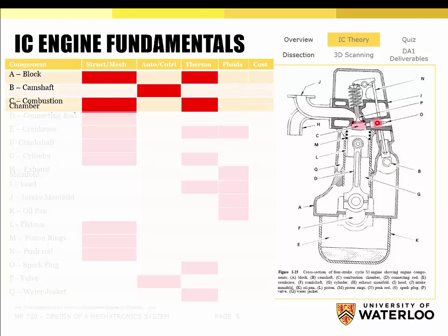So now the combustion chamber is this little red volume in here. The piston, which is this part here, we haven't gotten to it yet, but it's pretty much at the top of the combustion cycle here. So all the air that's entrapped here is the combustion chamber. As this crankshaft rotates and the piston comes down, the combustion chamber will expand in volume. Okay, we're going to look at that whole process in a lot more detail in a little bit. But this small volume here is pretty much the smallest volume the combustion chamber will take.